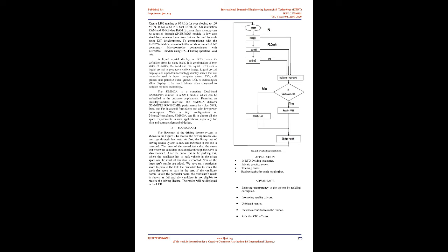The switch 10T85 is a snap action switch. It is connected internally in such a way that pins 1 and 2 are connected. Pin 2 is connected to pin 1 when the switch is closed. The switch is used as a crash sensor.